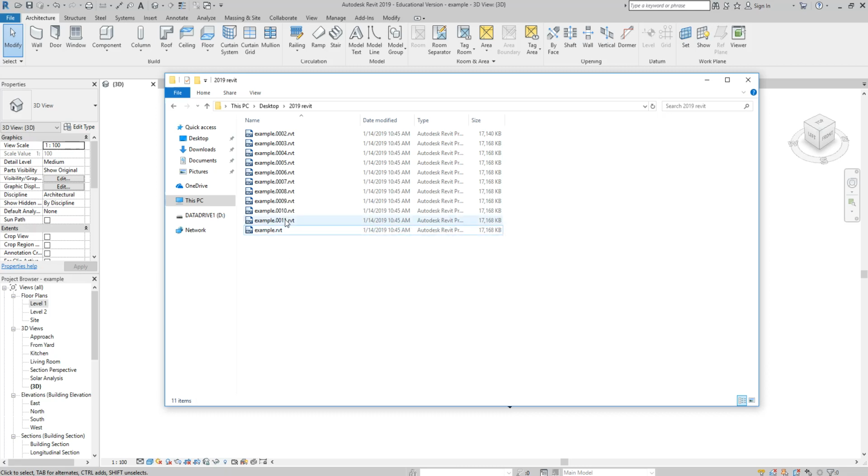Here's the one thing that I really don't like about Revit. This is something I've researched: they keep your backup files in the same place as your working file. I don't like that it has the identical extension that your working file has. And you can't change where to save them, essentially. I know the difference between a Revit working file .rvt and a backup file is really that there is this 4-digit numeric naming system that gets input into the backup file. And that's really it, right?